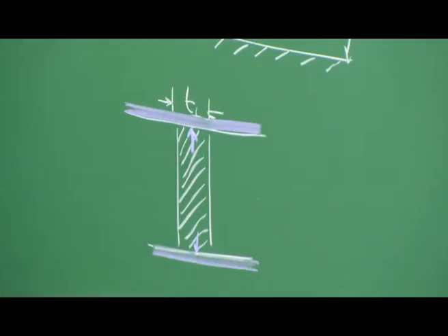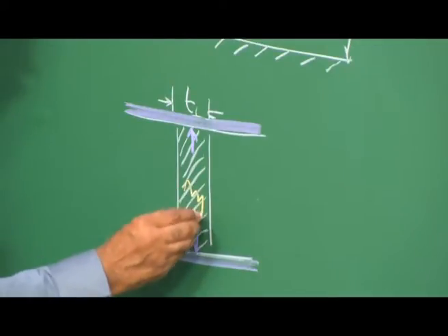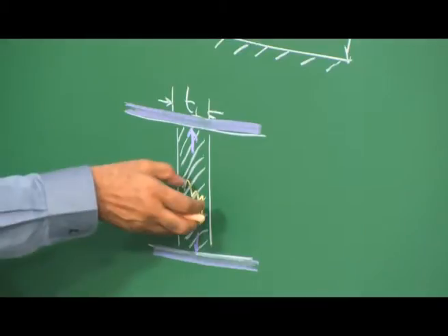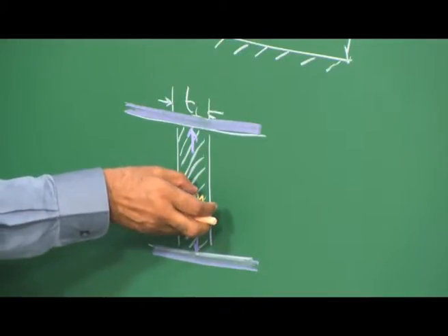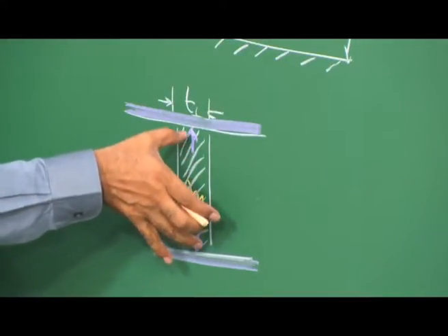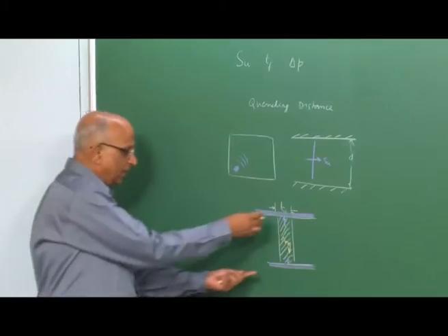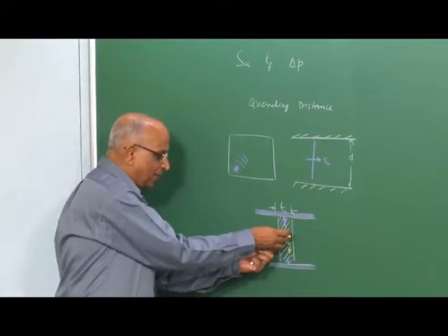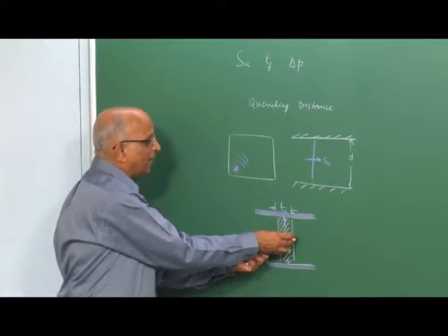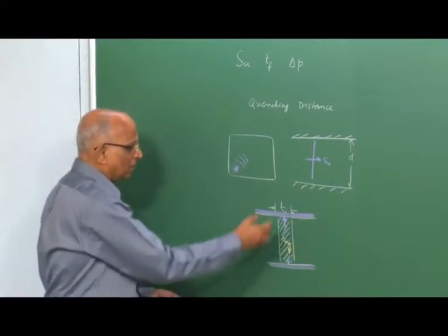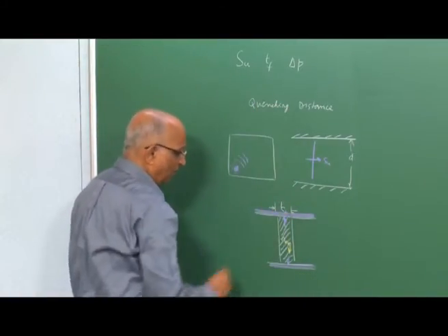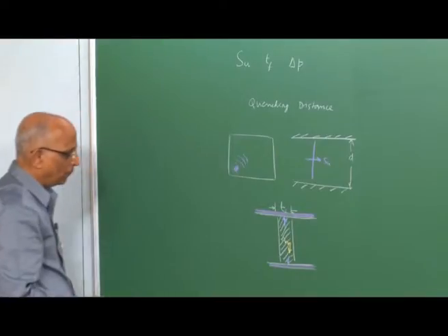But along with the heat loss, some heat is also getting regenerated or created within the flame, and therefore, there is a balance between the heat which is generated by the flame and heat which is getting lost. If the heat lost from this zone of flame is greater than the heat which is generated, well, the flame will collapse, and I can calculate a critical thickness or a diameter d for which maybe I have quenching of the flame, and that is what I want to work out.